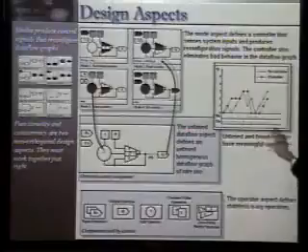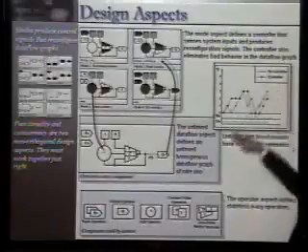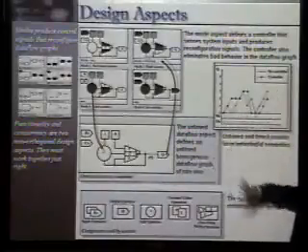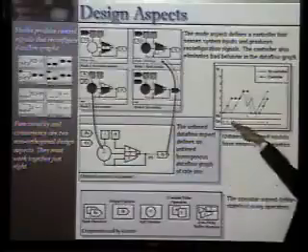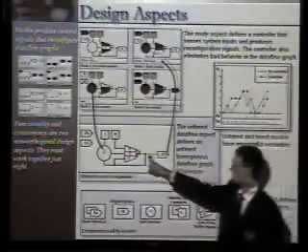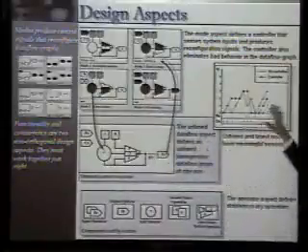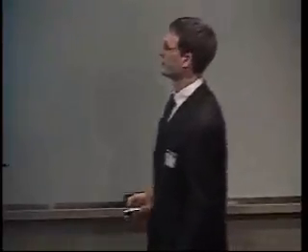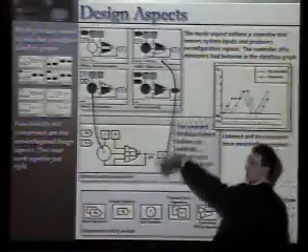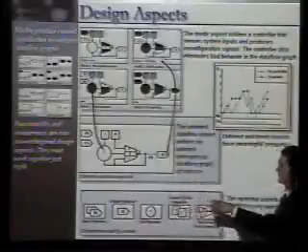You can simulate this with or without the controller. If you simulated this counter without this controller, just using the synchronous data flow semantics, you'd see some non-determinism where these signals are merged together. When you apply the controller, this non-determinism goes away, and you get exactly what you'd expect, which is this counter. And this makes the links between the different levels clear.